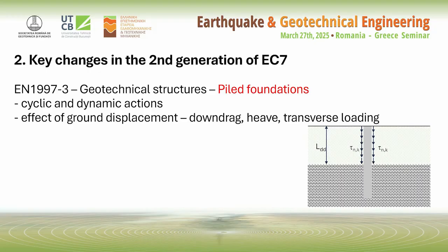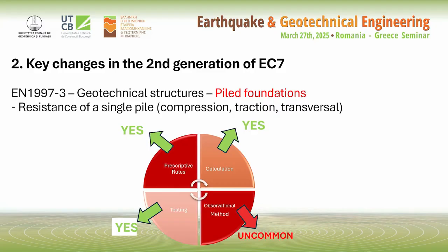In the part devoted to actions, we will find some new things regarding cyclic and dynamic actions, and also actions coming from ground displacements, as for example, down drag, heave, and transverse loading. And there are some calculation models, either simplified or more sophisticated. We can use either prescriptive rules, calculation, or testing, while the observational method is not so widely used in the case of piles, either for compression, traction, or transversal loading.